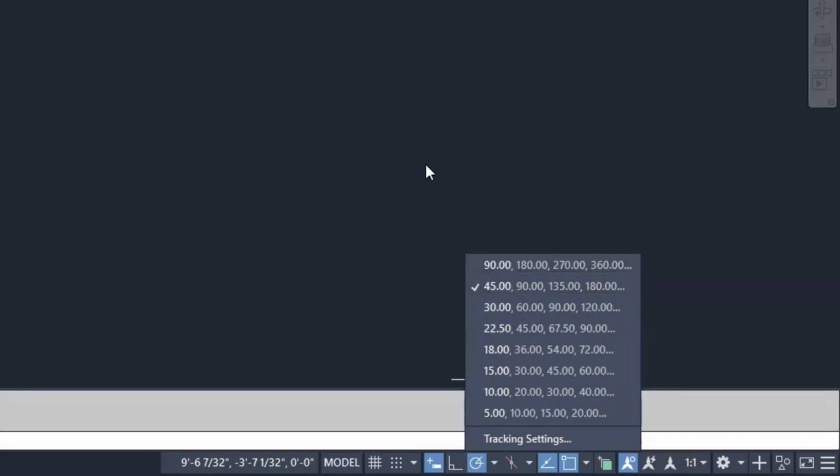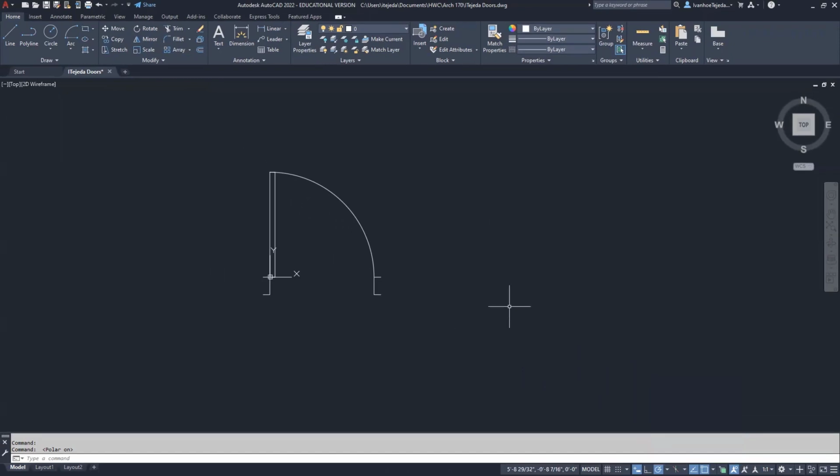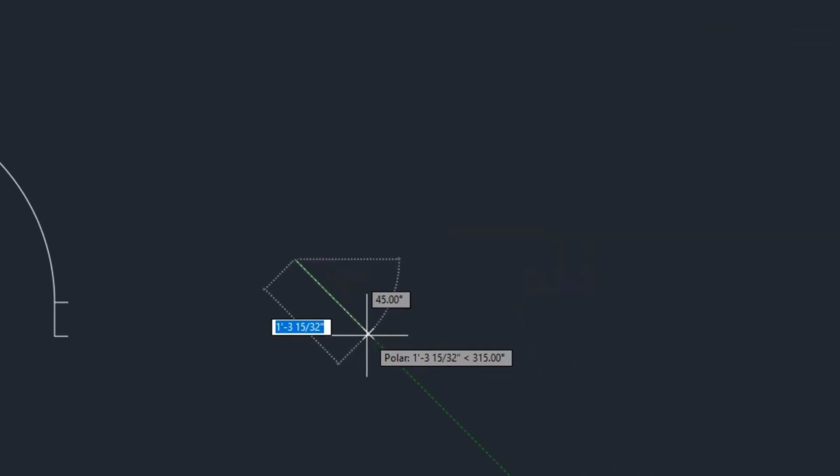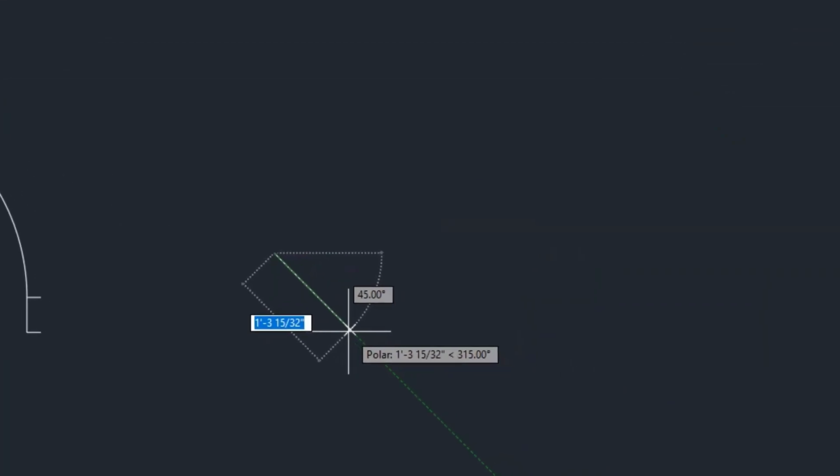So now I'll click away from that window, and I'll come over here, and I would like to draw the bifold doors in this location roughly. So I'll begin, Home tab, Draw Panel, click on Line, and I will select a point right here. I'm going to give it one click. And now notice, because I have polar tracking on, it's going to snap to every 45-degree increment. And I'd like to bring this line down and keep it at a 45 here. And that length is going to be 12 inches. So I'm going to type in 12 and enter.